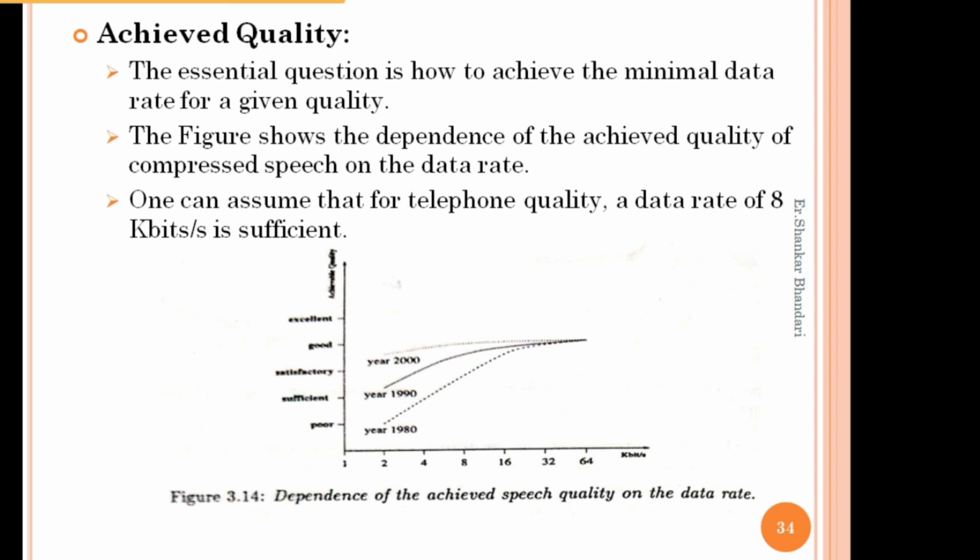The figure shows the audio quality and bits per sample, and the ratio shows for different signals like audio CD signals or telephone signals how many bits are transferred over the audio signal, which is achieved at the receiver side. The figure shows the dependency of the audio quality on the number of bits per sample value. For example, excellent CD quality can be achieved with the reduction from 16 bits per sample value to 2 bits per sample value. This means only 1/8 of the actual data needs to be transmitted.